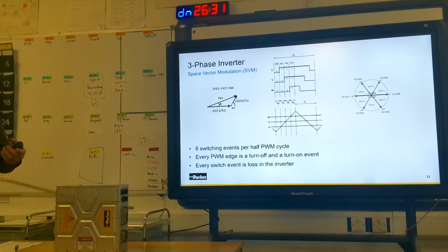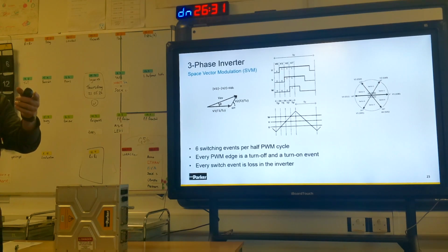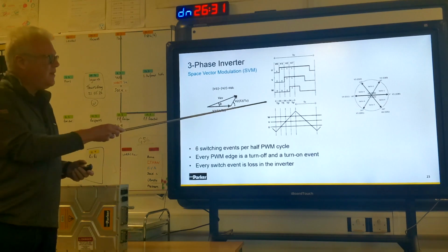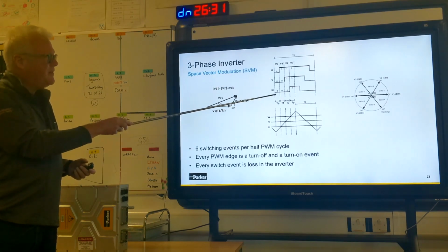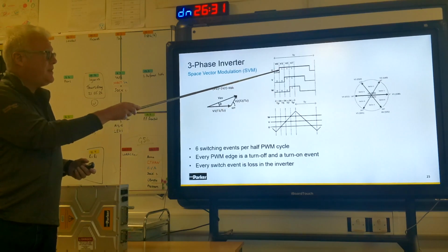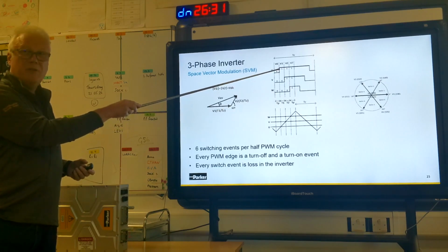What will happen is it will fire off a peripheral pin on the microcontroller. You can send that to a gate drive circuit, and that will tell a certain transistor to turn on or off. That's how it works. So here you can see the pattern starts off where we're at 0, 0, 0, or the three-phase short circuit lower. And then at a certain period of time, we turn on for a period of T1 just by switching one switch. It's pretty cool.